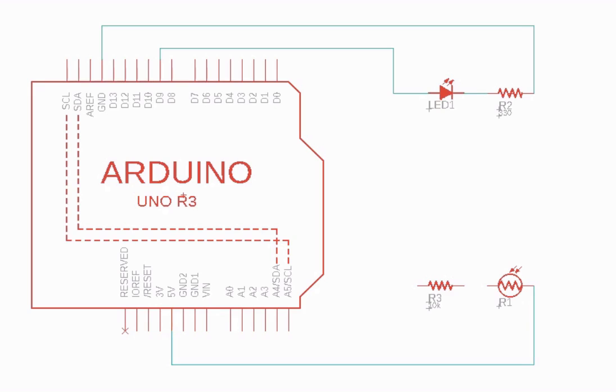It's going to be connected to our photoresistor. Our two resistors are in series, and we're taking an analog input measurement from port 0 at the point in between the two. And then this second resistor connects back over to ground.